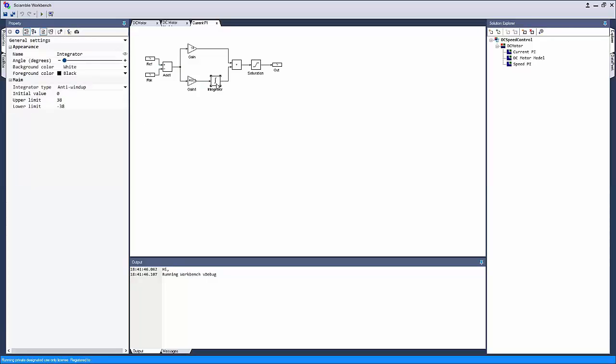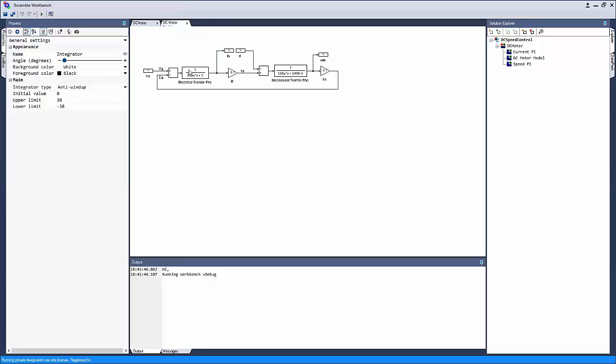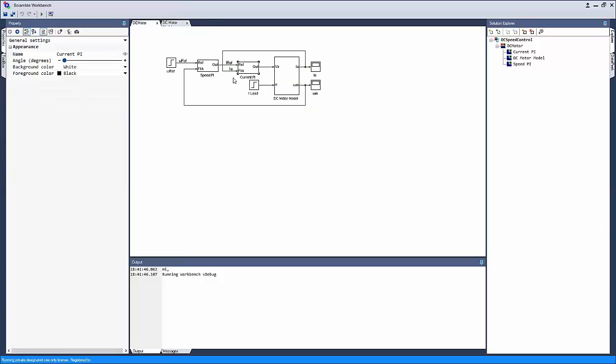And similarly, the integrator also needs to be saturated. If we don't use anti-windup in the integrator, we would end up having sustained oscillation due to the nonlinear limit cycles that will be introduced. So that is the inner current PI loop. We have a reference current and we measure the actual current, and the error goes to the PI controller, which is going to generate a control voltage, which is going to adjust the current so that the actual current matches the desired current.